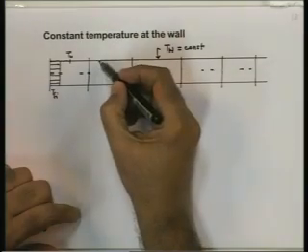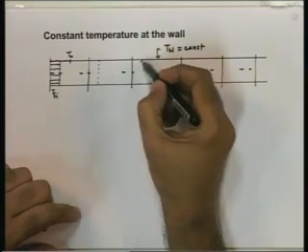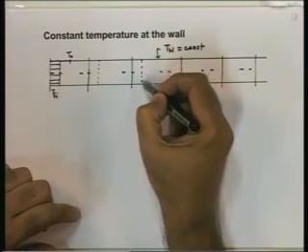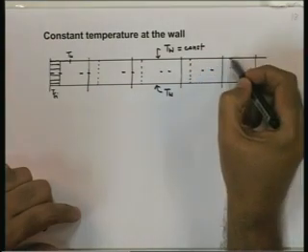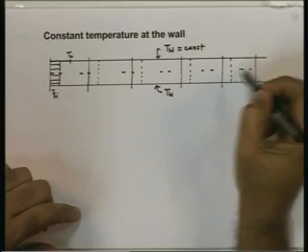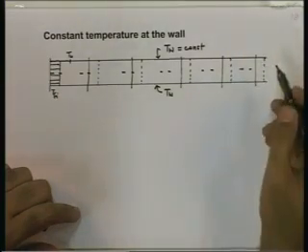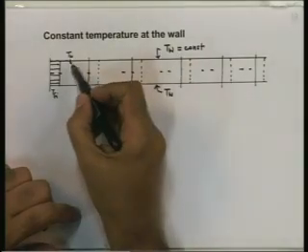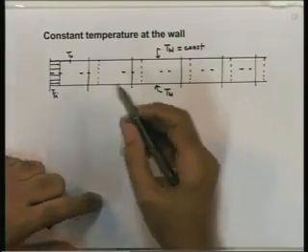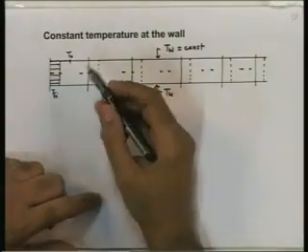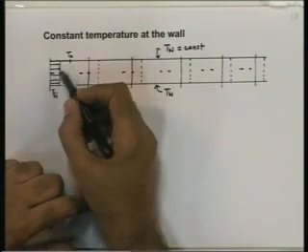If there were no heating, the temperature profile would remain what it was, equal to Tfi. Suppose the wall were insulated, this would have been the temperature profile. But the wall is not insulated, it is at a temperature higher than the fluid inlet temperature. So there will be some heat transfer from the wall to the fluid.